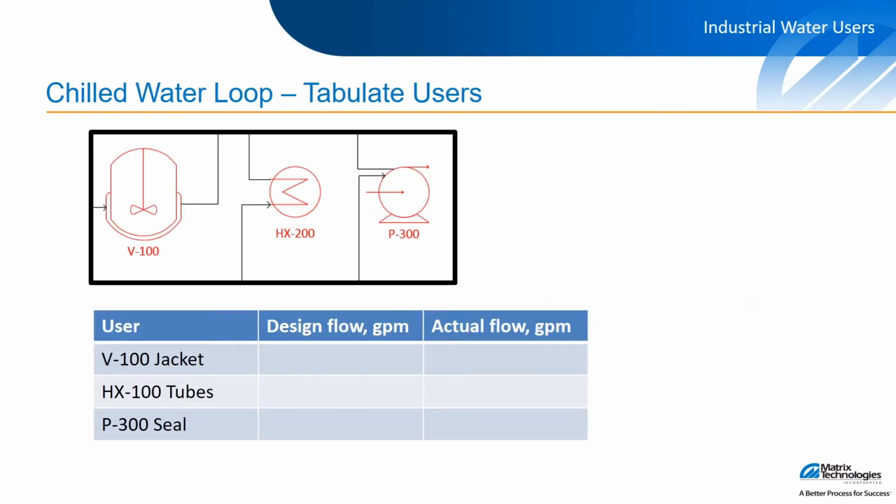The actual water usage can be calculated in different ways depending on your process. If you have a continuous process with installed flow meters, use the flow meter readings in the data historian as a comparison. If your process is batch-oriented, use the equipment information to calculate the water needed for each batch and the production schedule to calculate the number of batches over a specific time period. The time period will most likely match the dates of your water bill for a direct comparison.